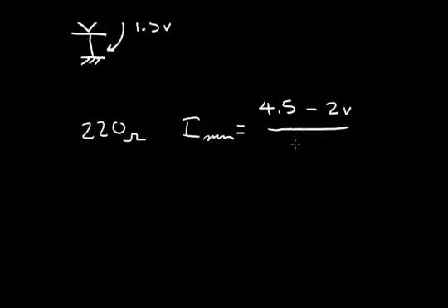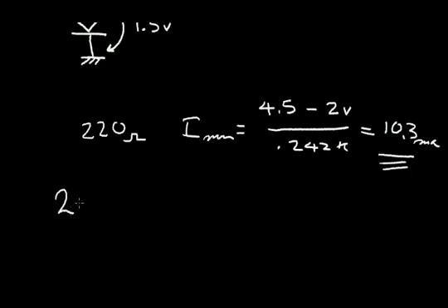And if the 220 is a little bit on the high side, at 10% high, 242 ohms, this will give me 10.3 milliamps, which is a little bit far from my ideal 16 milliamps. So I think that I'm going to prefer to use the 200 ohm 5% resistor,